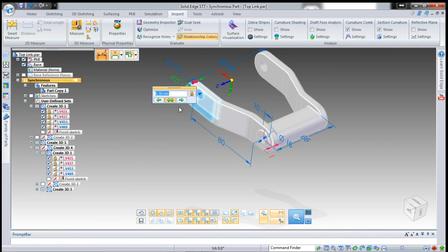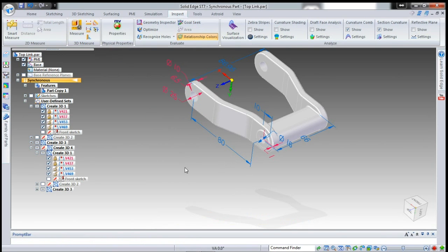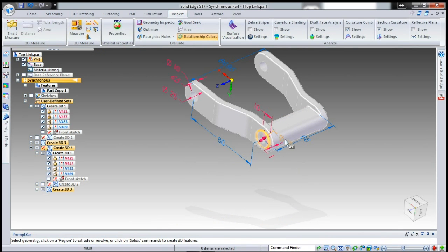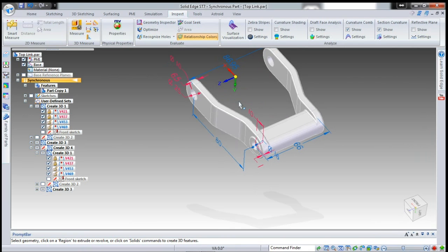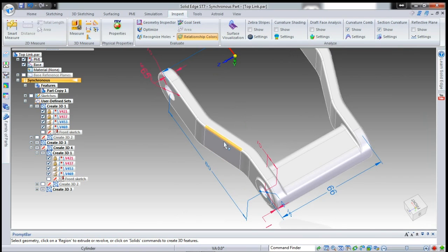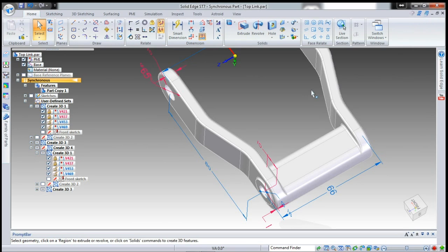You know, I can go through, I can lock dimensions as needed. I don't want any of them to change, so I'm just locking those dimensions. Now, I may need to make some fairly drastic changes, and one thing that isn't on here, it's just assumed, is that the width across this section is the same as this 6.5 millimeters there. There's no actual control over the geometry here.